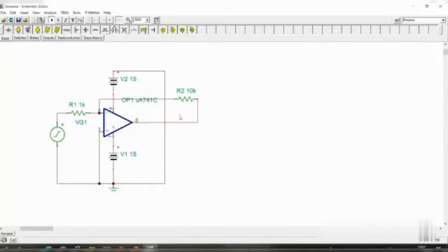And you need to check the input as well as output. For that, here you can see the meters. I told you the meters, a voltage pin can be clicked and dragged to this so that you will get the output from the 6. Okay. And if I want to check the input also, click again the voltage pin. If I need to rotate, in the sense this point should come here, then what I am doing is just click on it. Like this, one hand icon will come.